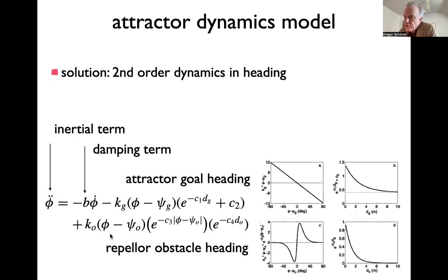If you just were to do this on the robot, and you introduce a real conflict, like an obstacle that really forces you to move in the opposite direction of the target for a while, then this would be quite wrong. You would get an instability: if your heading crosses to the opposite direction of the target, there would be a jump from a very negative to a very positive value. It would be really awful.